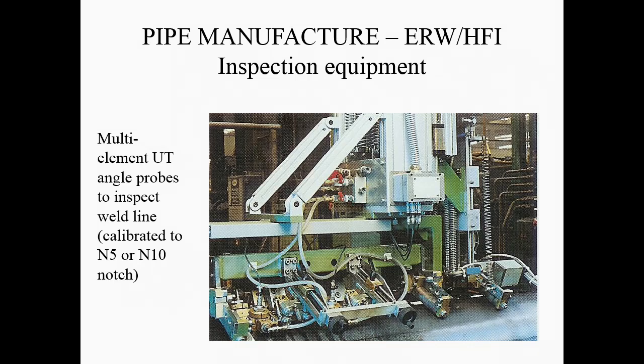There is no economic process that requires holding something for a long time at 600 degrees C. So you wouldn't see that. So within the time of this process, which is a few minutes, the rest of the material's microstructure does not change. And you try to adjust the inductor shape and the heating so that it's just along the weld line, and it heats the weld and the heat affected zone either side of the weld.